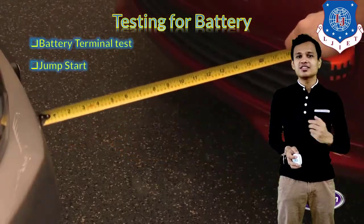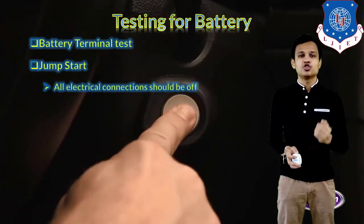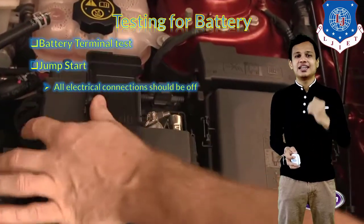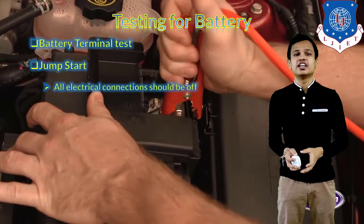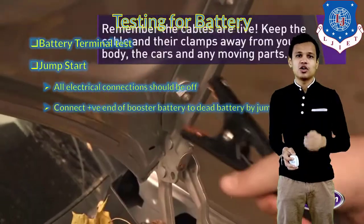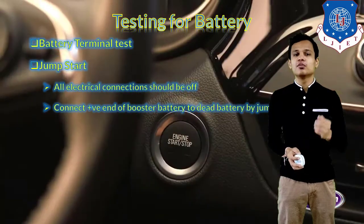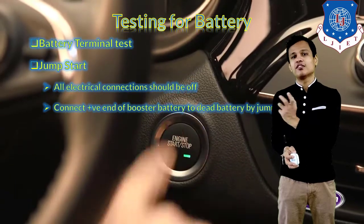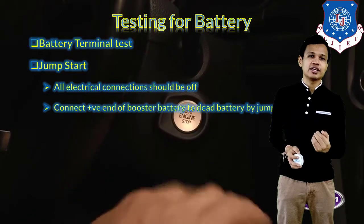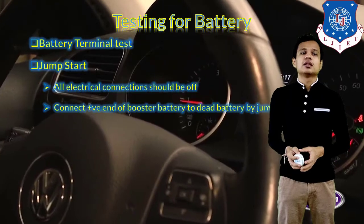For the jump start, the first thing that needs to be done is that all electrical connections should be kept in the off condition, such as headlights, music systems, tail lights, etc. After switching off all the electrical components, we will connect the positive end of the booster battery, that is the battery of our running vehicle, to the positive terminal of the dead battery of our vehicle that is not running, with the help of the jump cables.